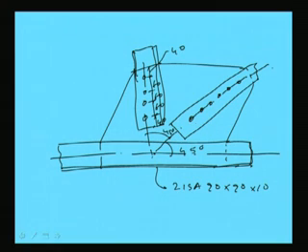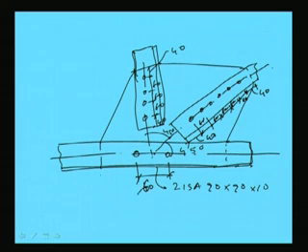Accordingly we make the pitch. The edge distance is 40 and these are all 60, and again 40. In the bottom chord we have 2 rivets, which we can provide as 60 and 40. In this way we can draw the joint.